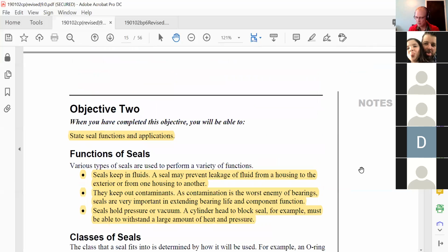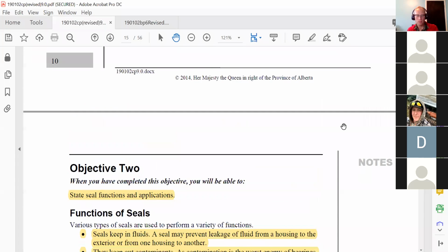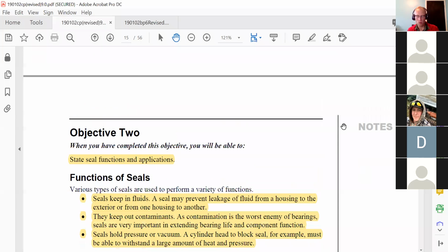So we just talked about bearings. What does a bearing do? Anybody? Reduces friction. Yep. So that's one. There's three more things that a bearing does. Protects wearing surfaces or eliminates them. Yeah, so reduces friction, protects against wear, or holds the load so that it doesn't wear components. Another good way to term that is it provides a replaceable wear surface.